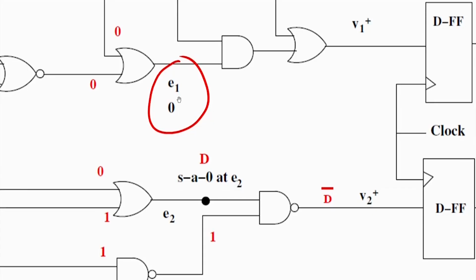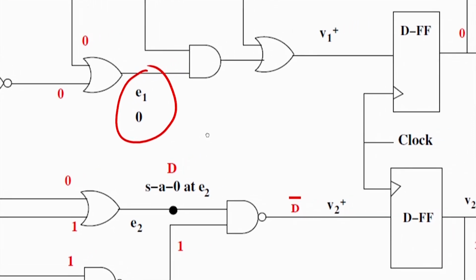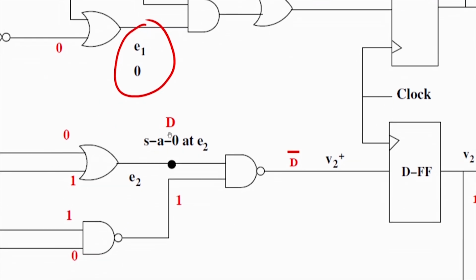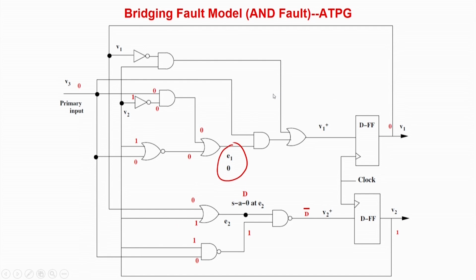Okay. So these are stuck-at 0 faults. I have to apply a 0 over here, which is the additional constraint, and then I go for propagation. Again, as we are having a scan circuit, I assume that the flops are not there, and I just go for something called a normal ATPG. So normal ATPG means for stuck-at 0, I apply a 1, D inverter, D prime, that is what I am propagating to this, and here I require an additional 0 over here.